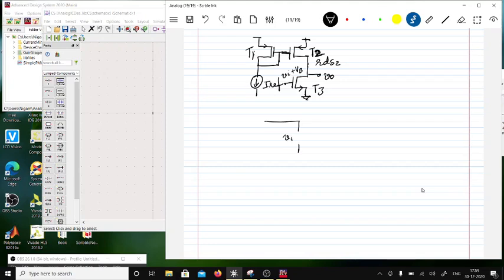Now I can consider VI over here, plus minus. This is the gate input. Forget about the DC bias, it is 0 volts for AC analysis. And then I have GM3 over here, and then I have GDS3, and then there is a GDS2, right, and that is to ground.